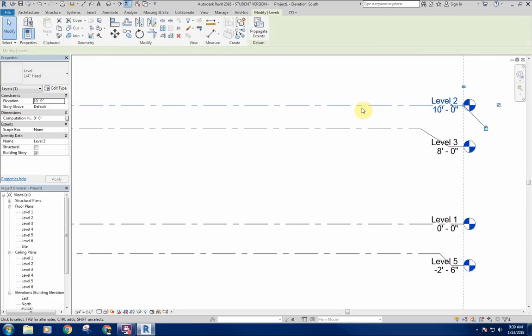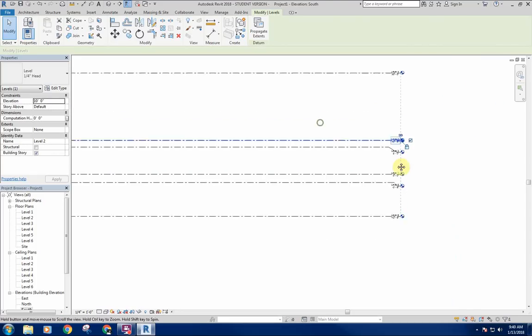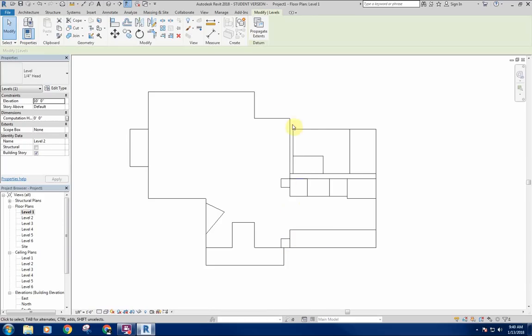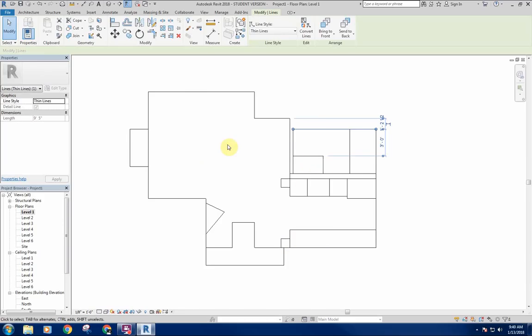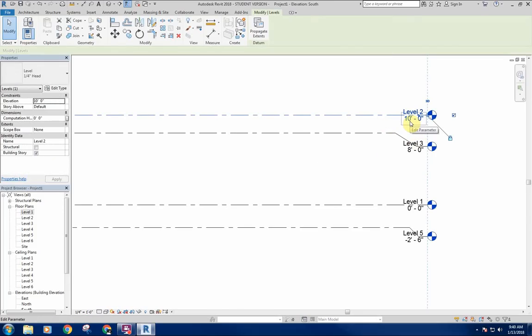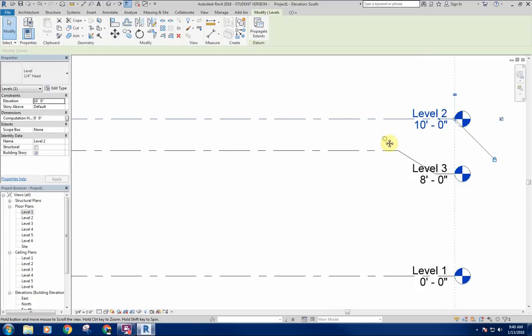So once I have my 8 foot figured out and know where I'm going there, my floor system, since I'm not going to have too much space there, I'll just go ahead and make this a bearing point here. I can span across here, which is going to be about 10 foot in span. So I can probably get away with, let's see, if I've got a 1/2 inch of drywall, 3/4 in my subfloor, that's 1.25 inches.